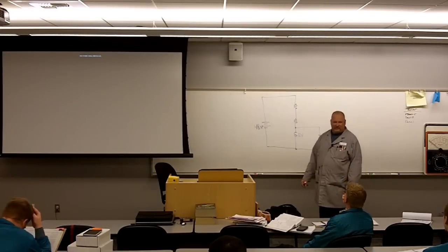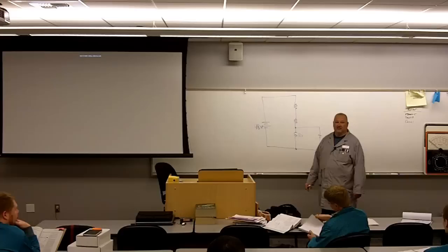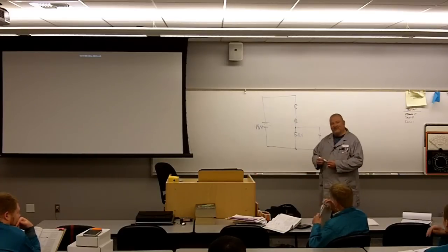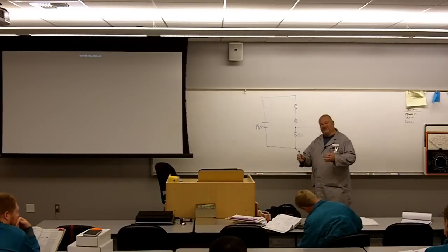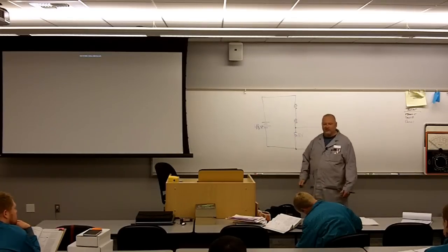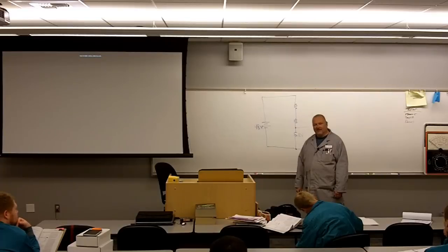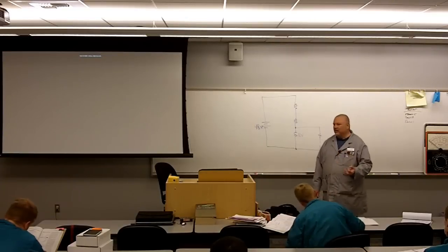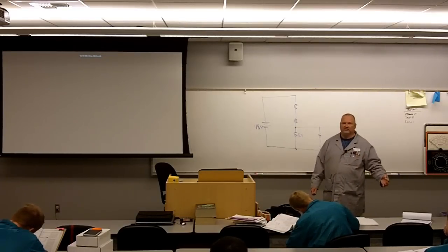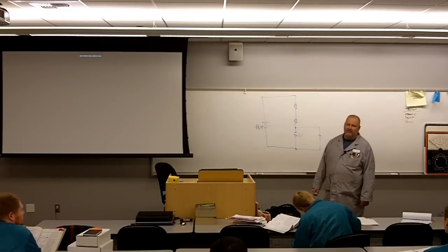Quite frankly, a voltage divider in and of itself, without any loads connected to it, is kind of stupid. If you had read ahead and had mastery of it when I was showing you the voltage divider, you could have said, Joe, that's stupid. What are you going to do, just put three resistors and divide the voltage? What good is that? What you've got to do to make it viable is connect a load to it, a loaded voltage divider. This is a real circuit. We're really going to power a CB radio.